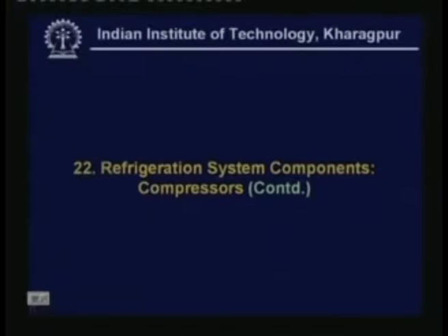Welcome back. In this lecture I shall explain the selection of principal dimensions of reciprocating compressors with the help of a worked out example. Then I will discuss practical issues such as the capacity control of a reciprocating compressor and the different lubrication methods and selection of lubricants.